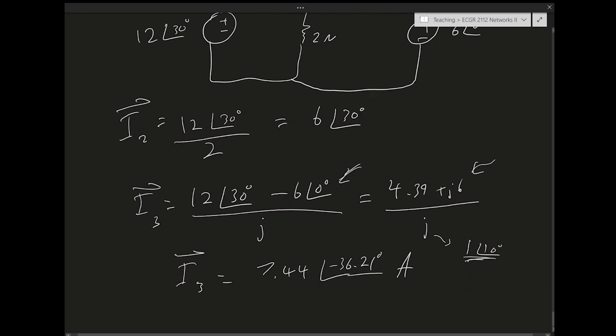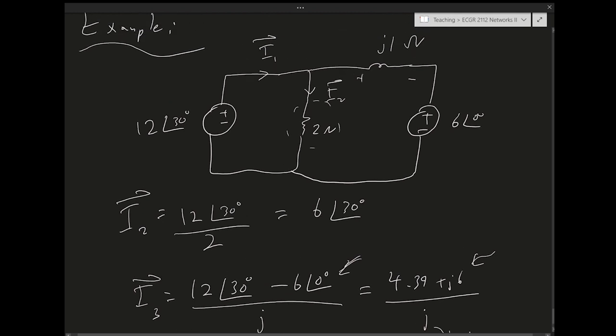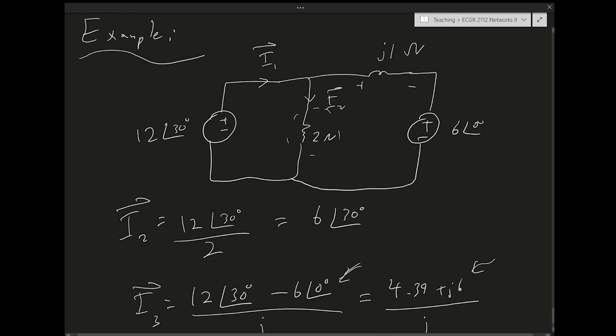Okay, so the only element that's absorbing any energy is the resistor, right? Average energy, average power. We know that the reactance, the inductance, is going to absorb 0 average power.